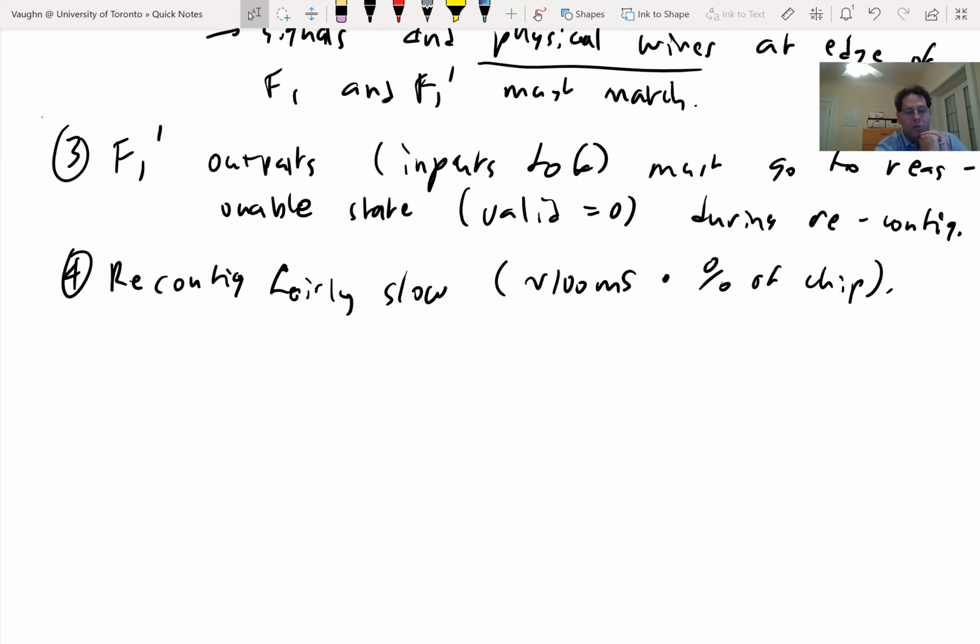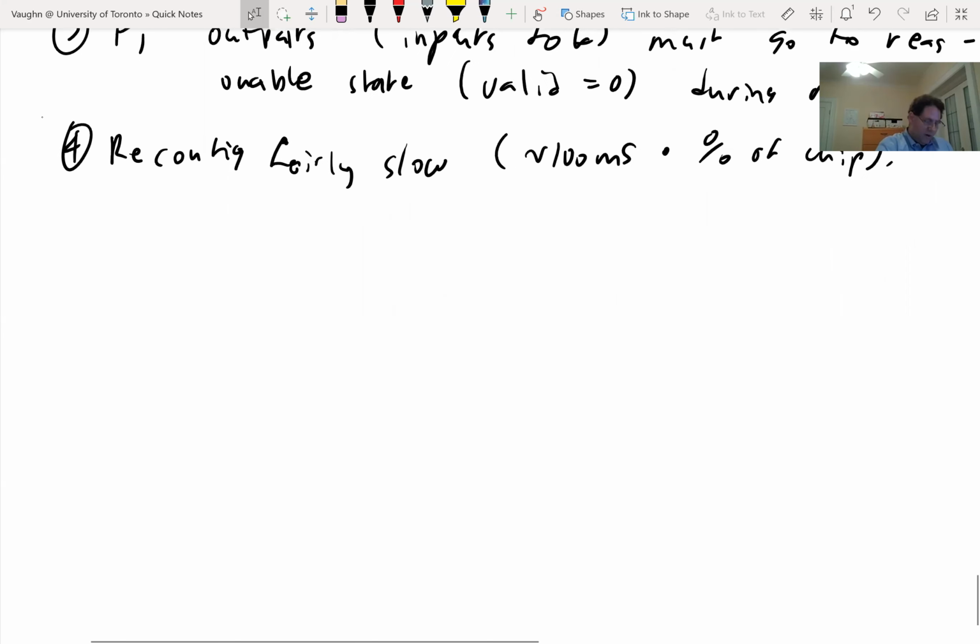But for the one customer that has decided to switch from Bell to Rogers, and we're talking big corporate class customers, it's okay for it to take 10 milliseconds to reconfigure that piece of the chip and put in a different protocol to connect to some other customer. So there are specific cases where partial reconfig is useful, but it is a more challenging design flow. So you need to sign up for the pain and use it somewhat judiciously. It's an interesting research topic: how could you make the CAD tools and the architectures more friendly to this? And there is some research in that area.